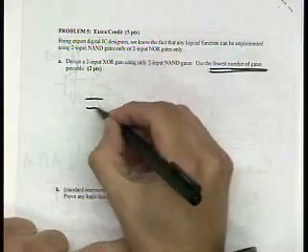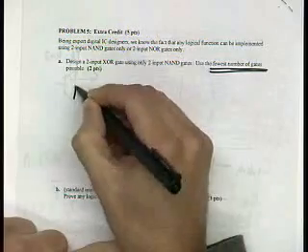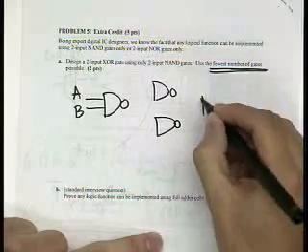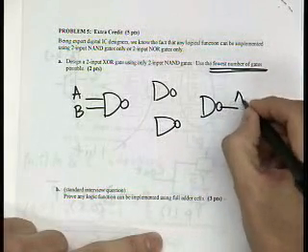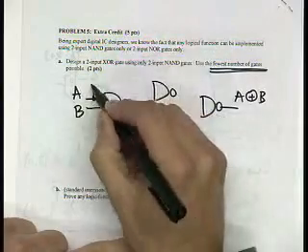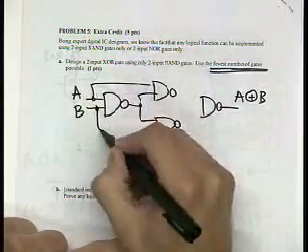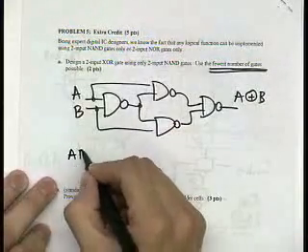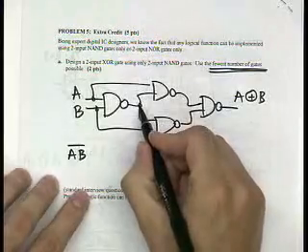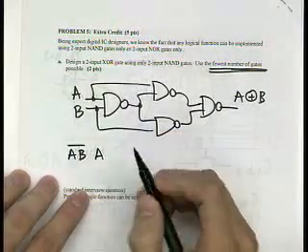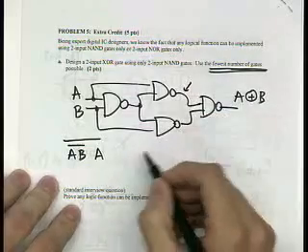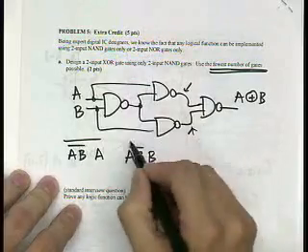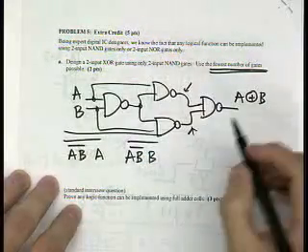here's the solution basically. You have, this is your A and B. Then you have another NAND here, and this is A XOR B. Connect it all up. So to convince yourself this works, at the output here you have (A·B) bar, correct? So then you have A NAND that, and that's the output over here. So the output over here is then A·(AB) bar, B·(AB) bar, and this all goes bar, right? So that's at the output.